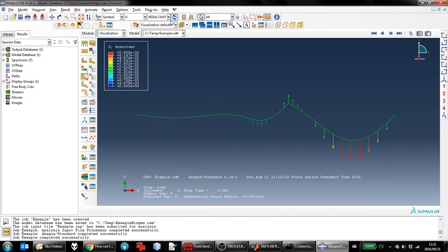Sometimes a vector plot is more informative if we go for the vertical deflection, for example. Again, the undeformed shape helps with it. What's interesting, obviously, from this is that because of the large load on the right span here, we're actually getting an upwards deflection on a portion of our deck over there on the other side of the support, sort of this overhang end. Right, so that's the basic functionality in terms of putting in hinges, and again showing how to do analytical loading.